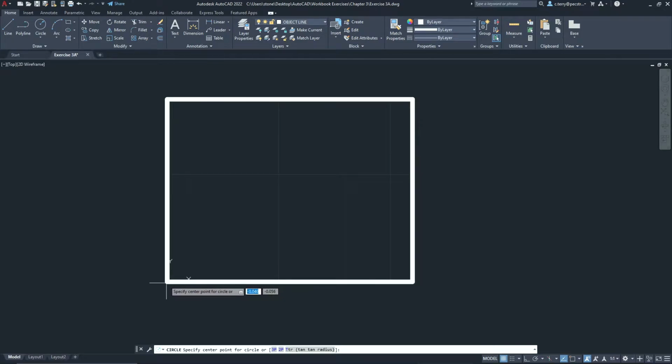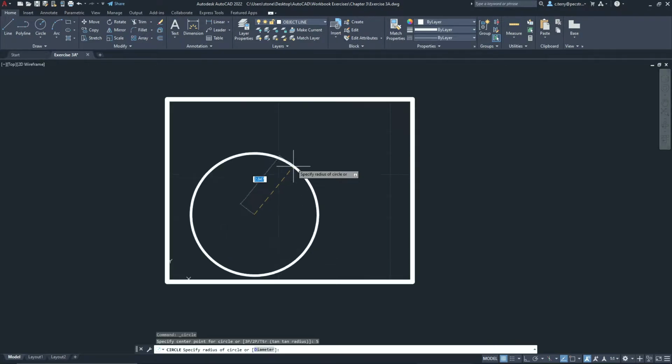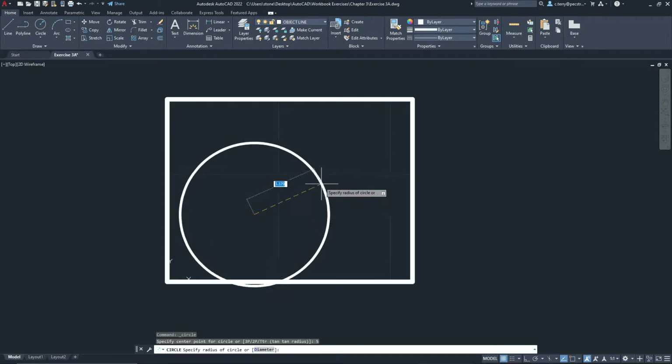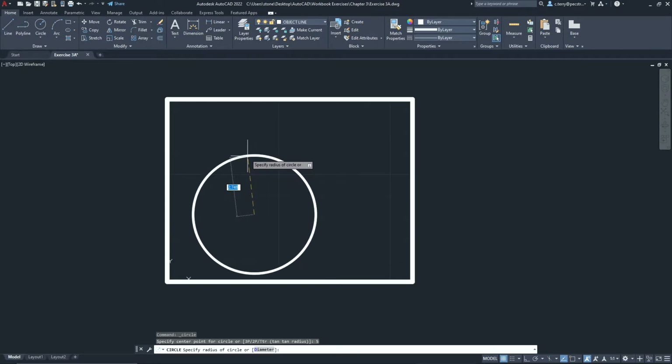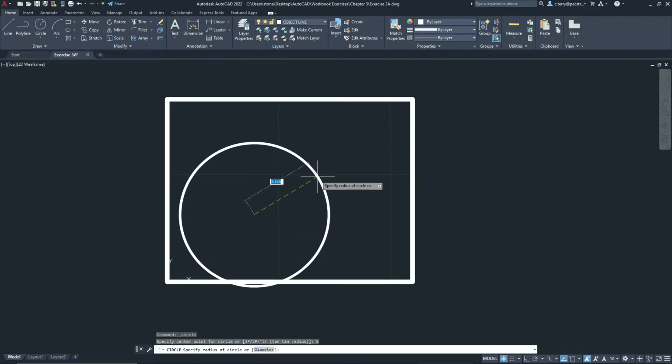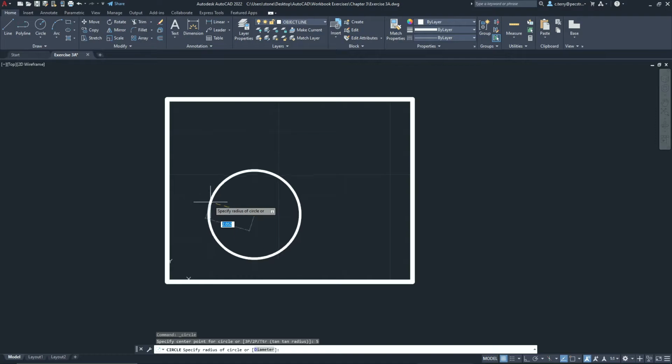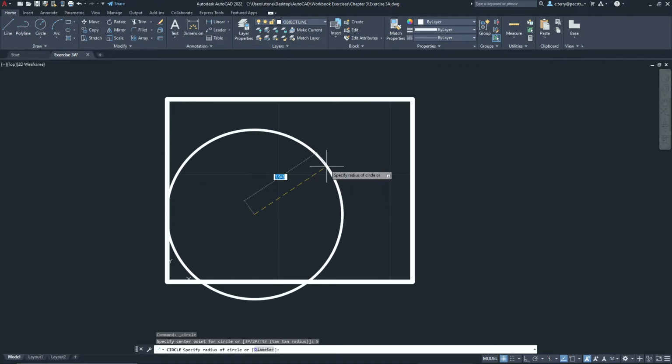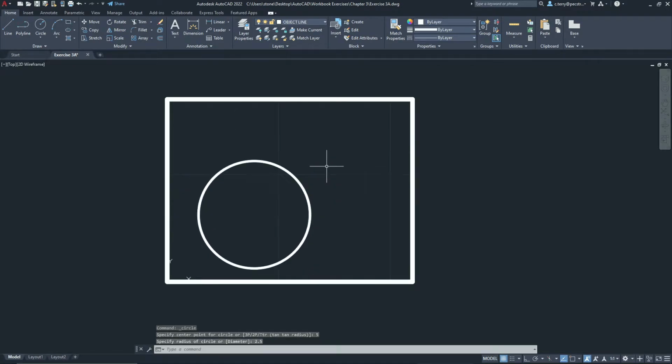So down here in this bottom left corner, that's going to be your 0, 0. I'm just going to pick somewhere over here, let's say 5 inches. And now that I've selected the center, it's asking me, okay, what's your radius to go out? You can see that I'm going from the center to the edge of the circle, the little dashed line. Let's say I wanted it to be 2.5. Click OK. Now if I come up here and measure the radius, it's 2.5.